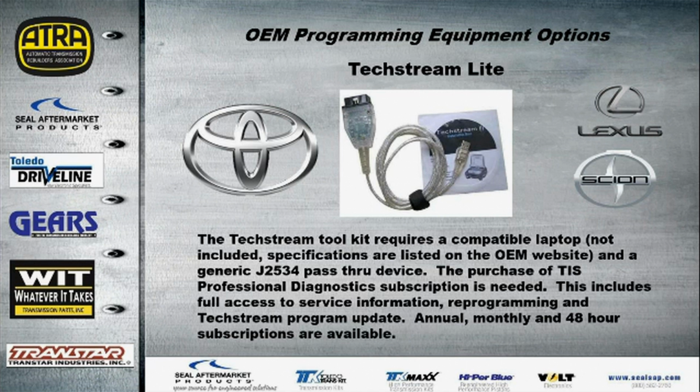Once you have this material, pretty much all that you need to do is have a laptop, of course, again, and the pass-through device, and you have to purchase a TIS Professional Diagnostics subscription. It's a lot like the subscription that we have for accessing the reflash sites on the other OEM websites.